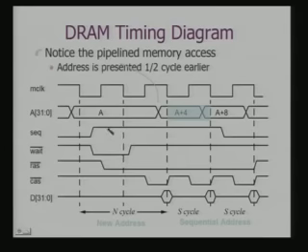So, when it knows that there is a sequential access, the wait need not be low. The RAS remains valid all through, and you are asserting CAS with different column addresses, and so you are getting the data from consecutive locations.